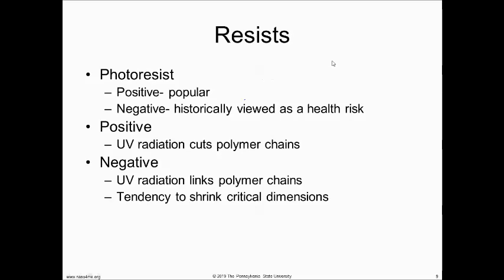So there are 2 types of resist. The ones we will be concerned with today, we're just going to stick with positive resist. But there's also the negative image of that, which is the negative resist. The positive resist is the most popular. Historically, the negative resist had more health risks associated with it, like birth defects. Right now, for the most part, most of them don't have that health risk anymore. They've designed new resists that don't have that. But for either resist, you want to be very cautious as far as health, because you are working with an organic polymer.